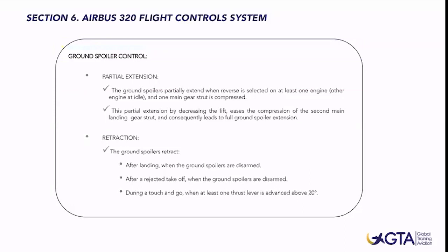You will see during the A320 course that we have basically two braking modes for the auto brake, low or medium. If we select low mode, the auto brake will commence the braking function just 4 seconds after the spoilers' deployment. If we select auto brake medium, the auto brake will commence the braking function just 2 seconds after the spoilers' deployment.